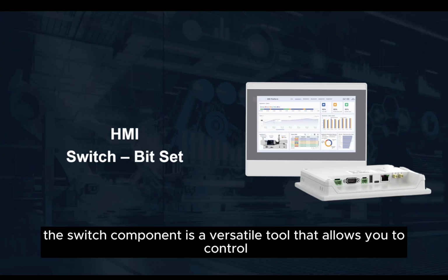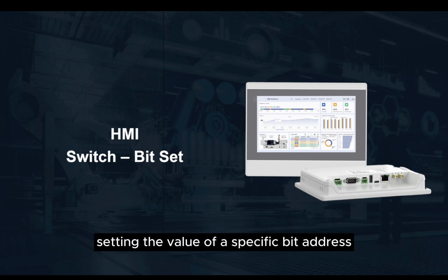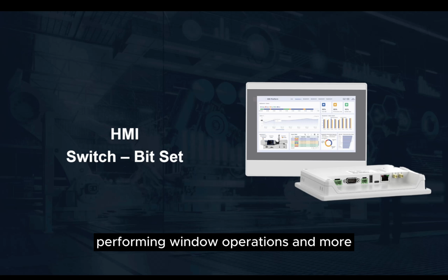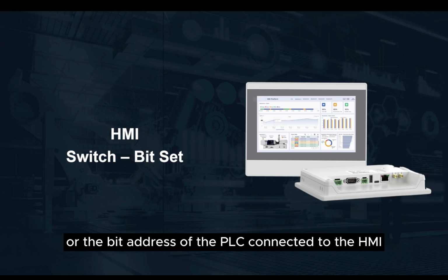The switch component is a versatile tool that allows you to control different states and execute various functions when the state changes. These functions can include setting the value of a specific bit address, transferring data to a PLC, performing window operations, and more. The bit set switch is a unique component that sets the value of the internal bit address of the HMI or the bit address of the PLC connected to the HMI.